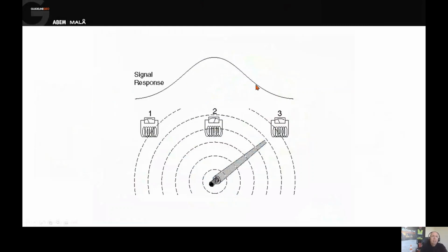And we get typically a peak response above the pipe or cable. There are some other techniques as well of different responses that we can get, and particularly we're going to use these for verification of the symmetrical shape of the signal, and that will then help us quantify things like depth measurement and the position, etc. So we're going to use that technique or technology first. Like I say, mainly we're going to use that for locating the metallic utilities.